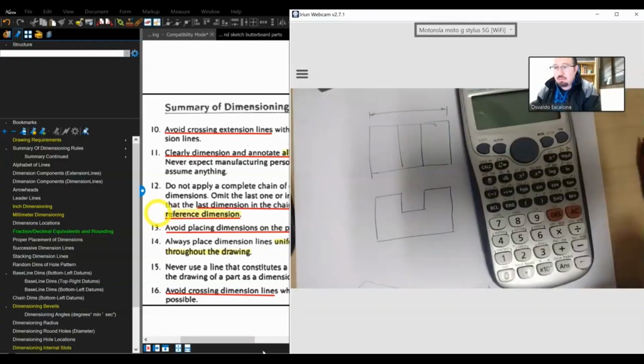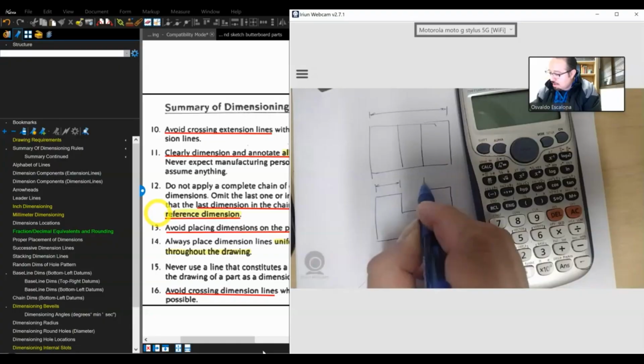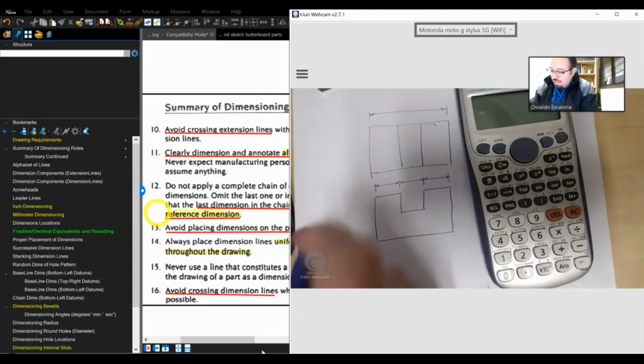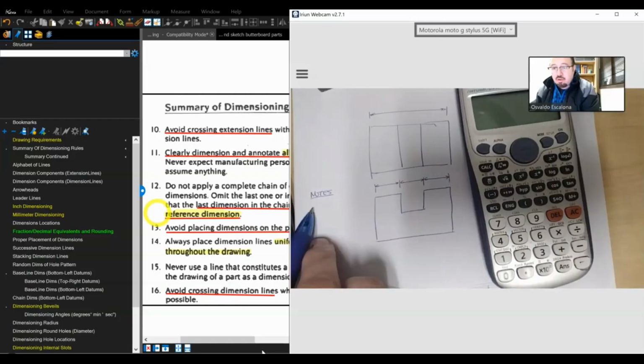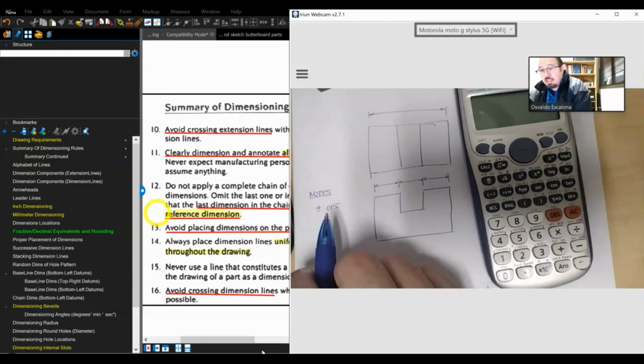Obviously, the resolution is for my calculator, so it takes it. And then somewhere over here, a guy says, you know what, I'm gonna come and give that dimension, and then I'm gonna give that dimension. Right? People that don't listen to me. And then somewhere in the notes it says, unless otherwise specified, for all linear dimensions plus and minus 0.015, 15 thousandths of an inch.